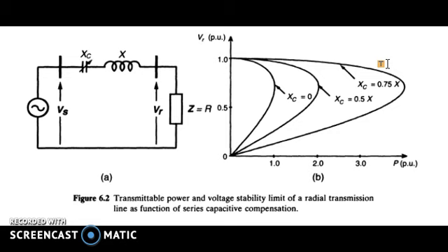Also, from the retrofitting or infrastructure point of view, for the same transmission line, the same generator, the same substation and all, by adding a series compensator, which is not that simple but is much less complex and much cheaper compared to other devices, we are able to transfer a much larger amount of power under the same circumstances.